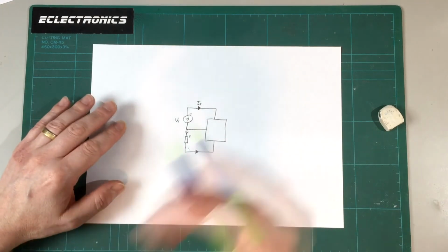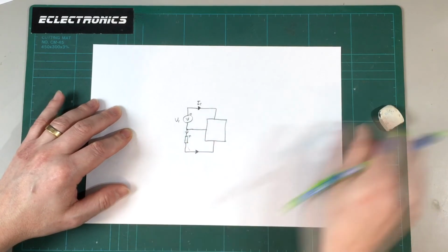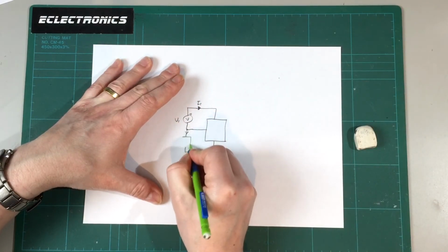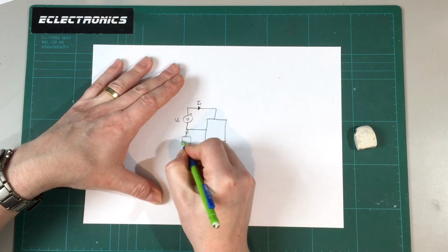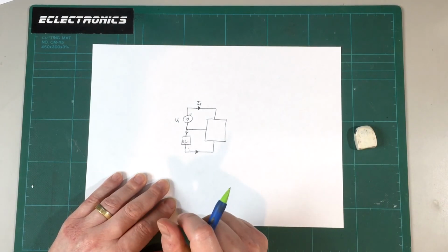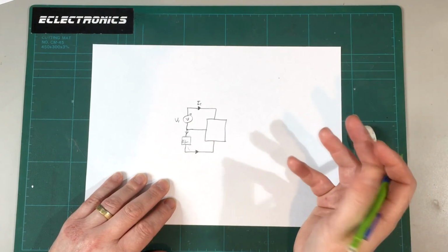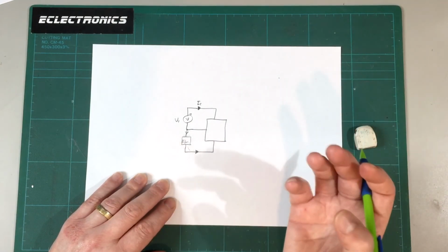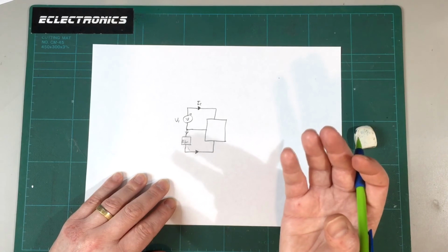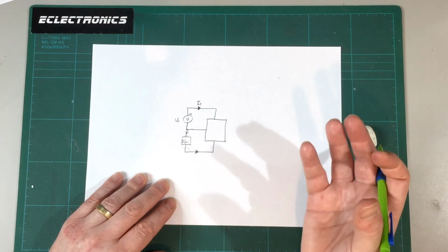So my idea was, what about if we replace this with an electronic load? So we get rid of this as a resistor, we connect some kind of black box here, which is an electronic load, and then we can control the voltage quite precisely because we can tell the electronic load to say keep the potential at, let's say, 3.8 volts and just draw whatever current you need to hold that potential at that level. So that should be a much more stable scenario, much more like a real battery cell, because it's difficult on a real battery to change its potential quickly because you need a lot of current to change it quickly.